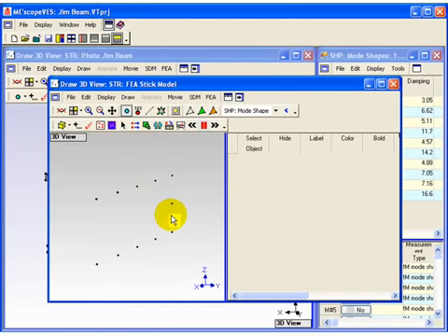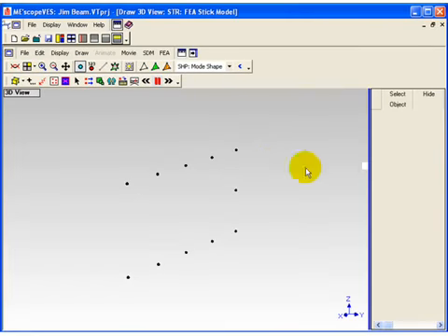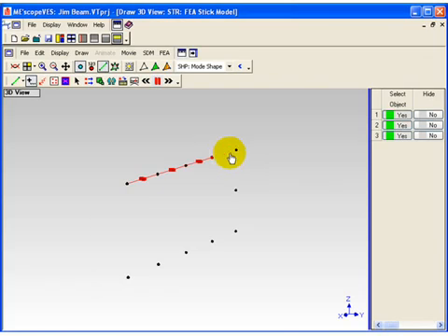To complete the 2D profile, line objects will be added between the points and all lines and points will be grouped into a new substructure. Select Lines from the Edit Objects list on the New Structure window toolbar. Execute Edit, Add Object. All of the points on the model will be displayed. Starting at one end of the profile, click on a point and then on an adjacent point to add a line between them. Repeat these steps until 10 lines connect all of the points in the profile.